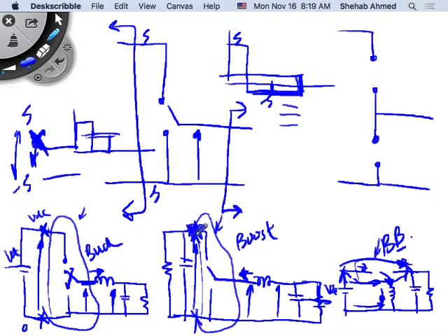This output voltage, in this case, it happens to be the output voltage, and its relationship to the voltage at the input, is what? Same thing. If the switch is up here for a longer period of time, then I would see a larger average value here. If the switch is down here for a longer period of time, then I will see a smaller value here. And it makes a lot of sense, because remember in the boost converter, this was my switch.